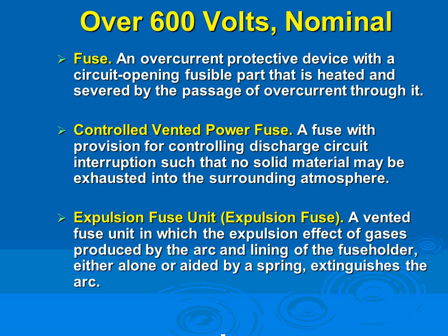When it comes to high voltage, guys, the difference between the high voltage fuse and low voltage fuse is, to help me understand it, always think of the fuse as not just amps, it's energy. When you have a 600 amp fuse, take the 600 multiplied by 600 volts and 1.73, that's how much energy that fuse can handle. Now, take a 10 amp fuse, high voltage, and multiply it by 13,800 multiplied by 1.73 and see how much that little amp fuse will interrupt. The amount of energy is huge, so look at it as energy. If you look at amps, it doesn't mean anything.